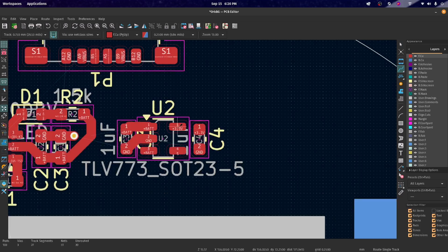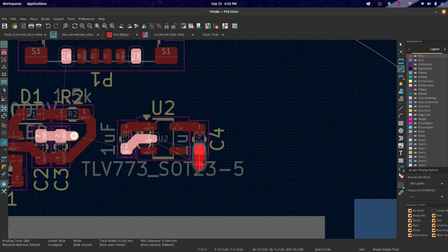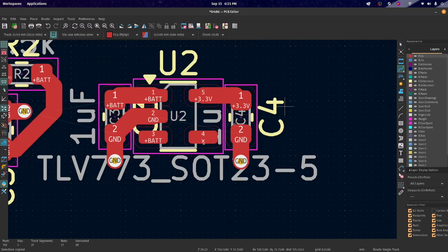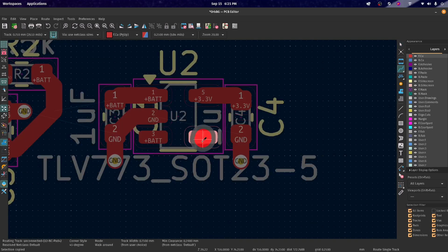I can connect grounds, and I am planning on having a ground plane. So let me get that situated. So I'm going to use a via to access a ground plane. This terminal, it did say to connect to ground.